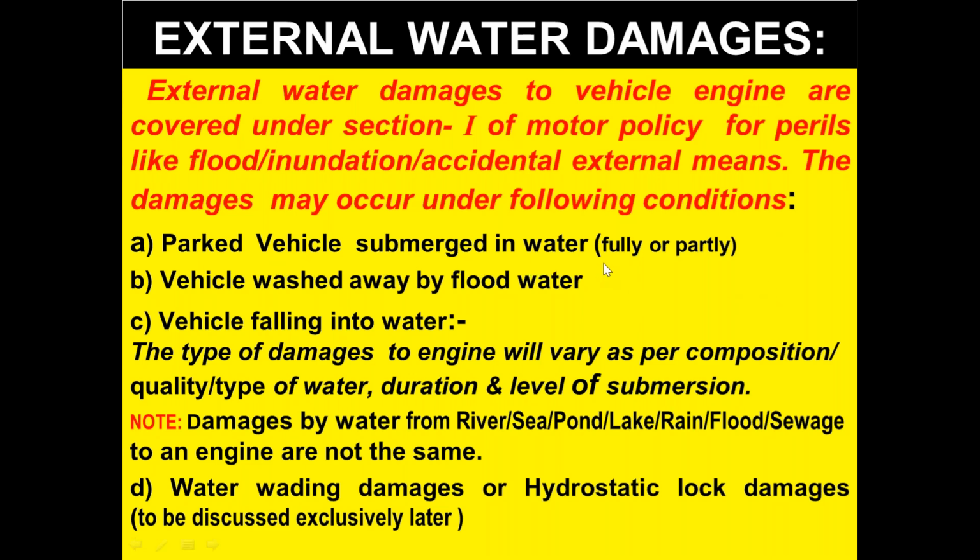Parked vehicle submerged in water, fully or partly. Vehicle washed away by flood water. Vehicle falling into water. The type of damages to the engine will vary as per the composition, quality and type of water, and the duration and level of submersion. Please note, damages by water from river, sea, pond, lake, rain, flood, or sewage to an engine are not the same. Water wading damages or hydrostatic lock damage will be discussed exclusively later.